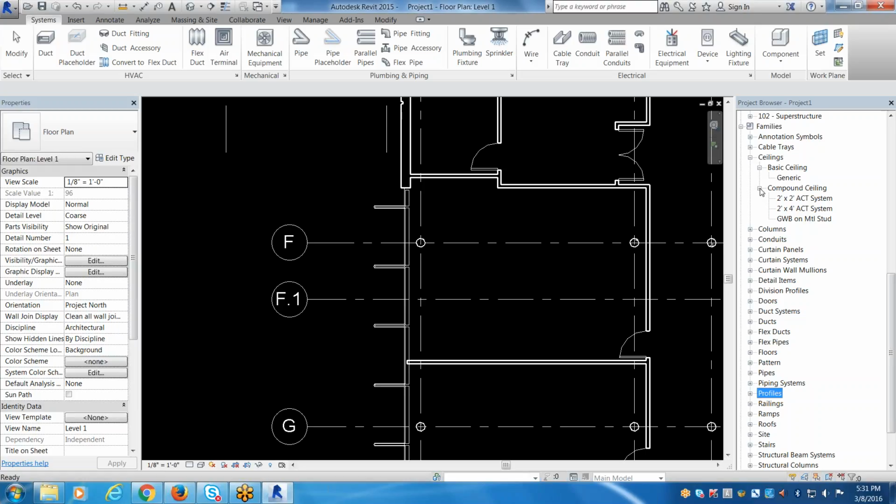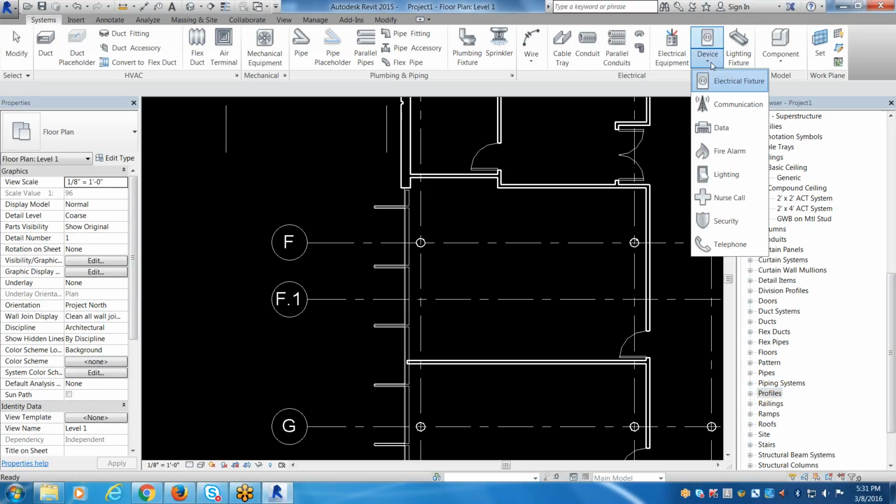So let's recap. The family category, when assigned, dictates where that particular family is placed here. And it's especially important for electrical stuff. Because with electrical stuff, let's say I make a duplex receptacle, okay? If I classify it as a nurse call device, then it's not going to work like a power device. Or if I classify it as a telephone, teledata, then it won't work like this.